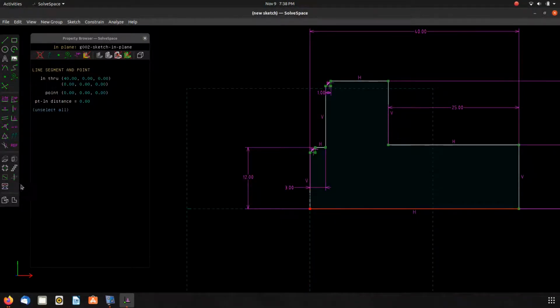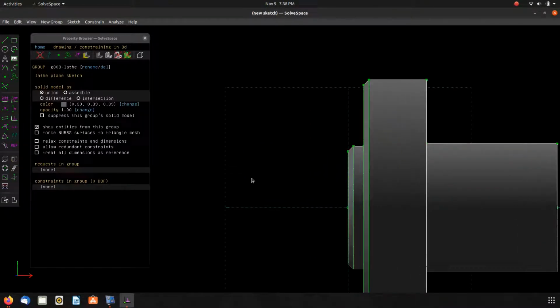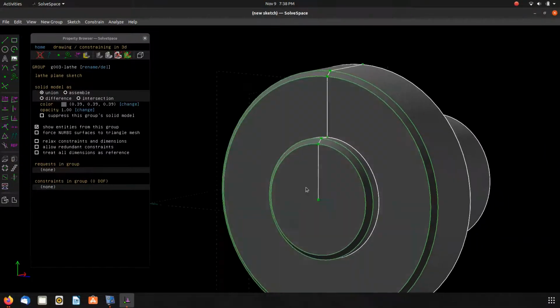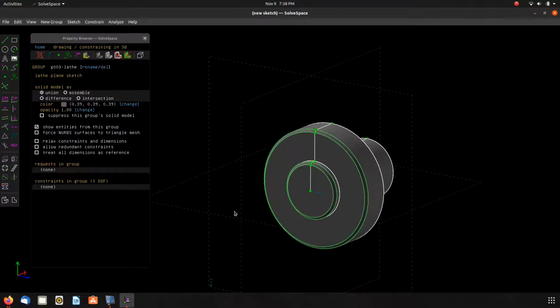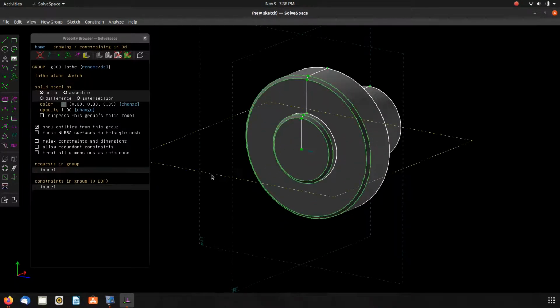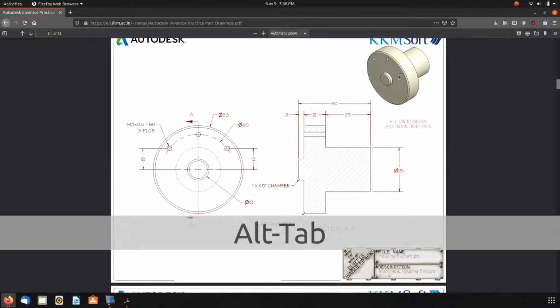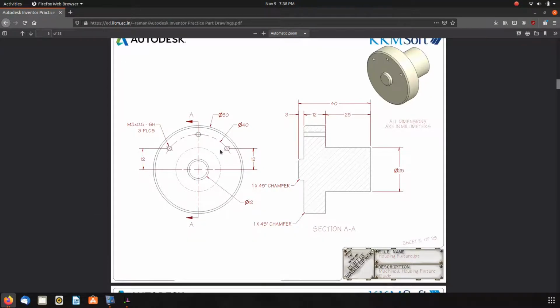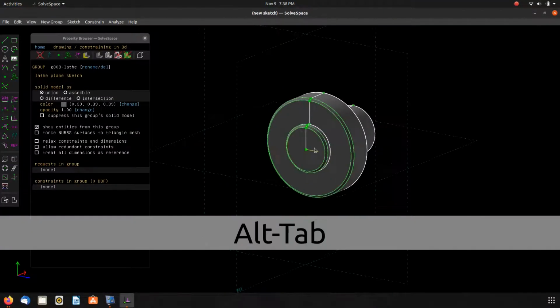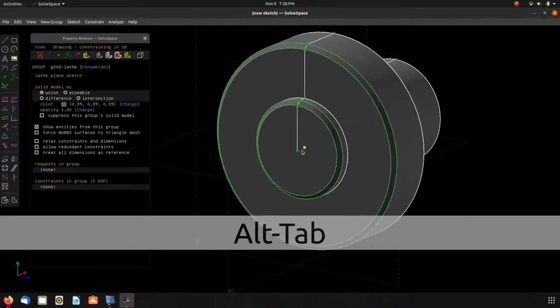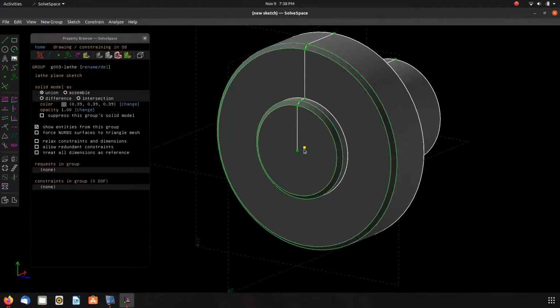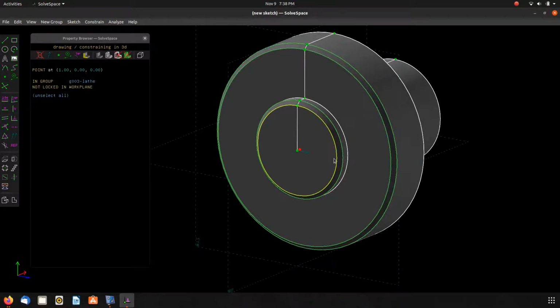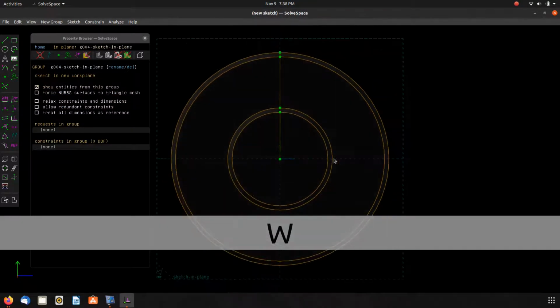Now, if it was a functional part, I would discover that error, hopefully before it was too late, upon review or something. But anyway, so now I'm going to put these holes in here. With most modeling, at least in the professional world that I've seen, putting in actual threads is more of a cosmetic thing than anything else.